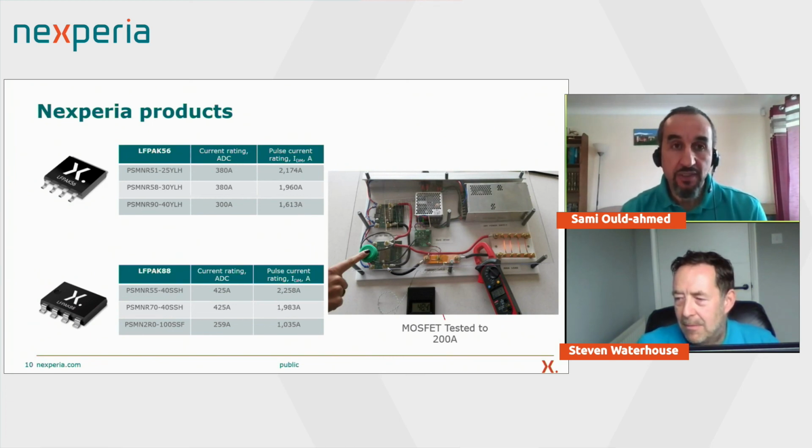The current rating that we state in the data sheet is verified through testing. By that, I mean we verify it through the time length that we are more than confident it achieves the DC rating. I mentioned more than 30 seconds, while the actual DC is within 1 second. On top of that, we cater for any parameters that provide the limiting factor.